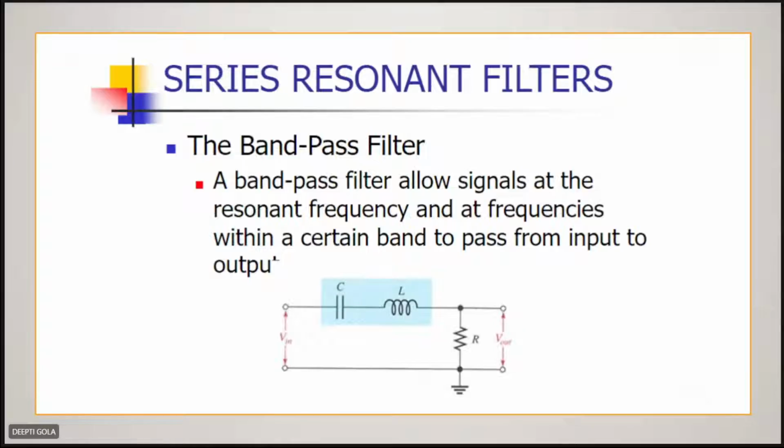Okay. So what is the application of this resonant frequency or application of this RLC circuit at resonance? So this is the application. RLC circuits are used in band pass filters. How? Because if we connect them in this way, with the reactances connected here and the output being measured at the resistor, right? So what will happen? This circuit will work like a band pass filter.